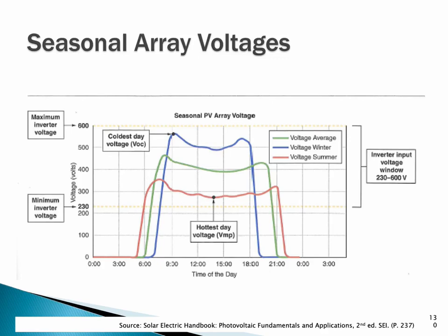This isn't necessarily a problem for the Midwest, but it is a problem for California, Arizona, New Mexico, these down in the Sun Belt region. On the opposite end of that, we don't want to go beyond the voltage limitations of the inverter on cold days, and that's what we're concerned with in the upper Midwest.